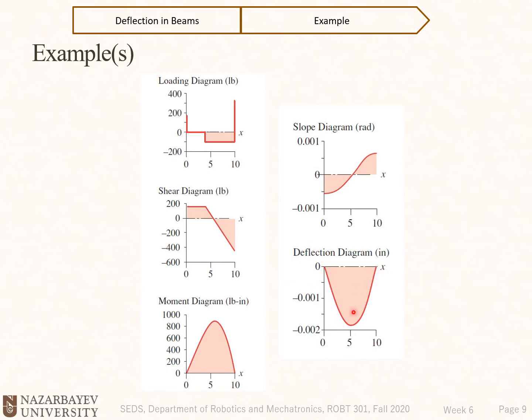What we need to know is that deflection at supports are 0. Okay, so at 0 and L, deflection is 0. Okay, these are our boundary conditions. Okay, another method is to use singular functions.